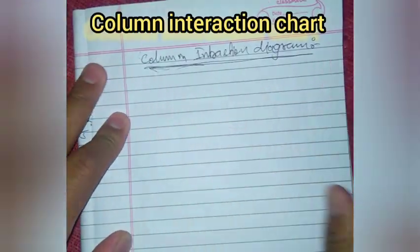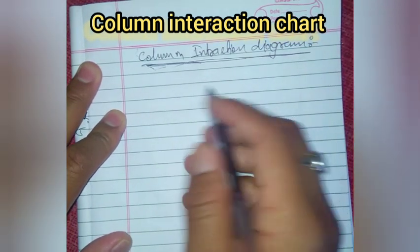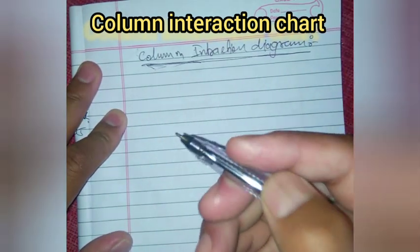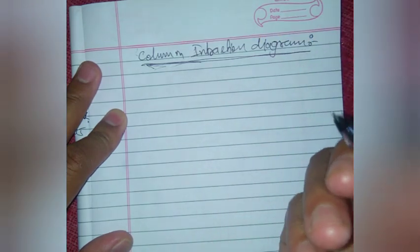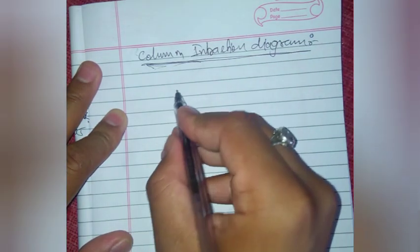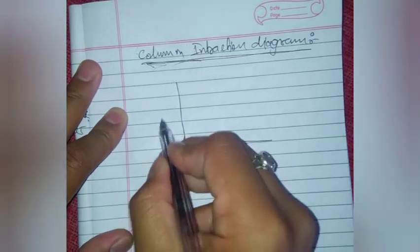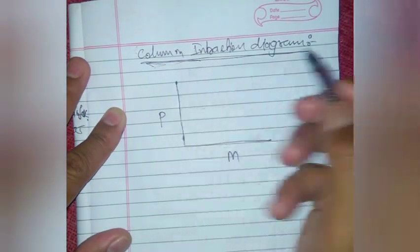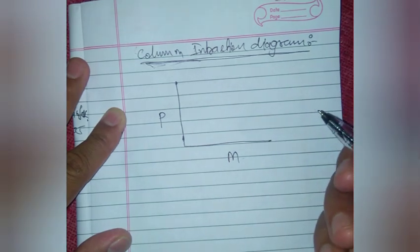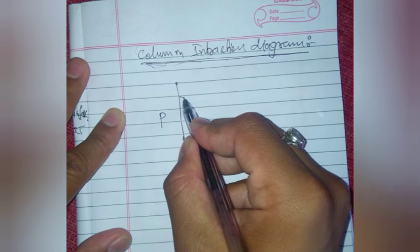What is in the column interaction diagram? We draw the curves for different areas of steel, different grades of steel, and different concrete. We draw a curve between Pu and M here. So the curve is like this.